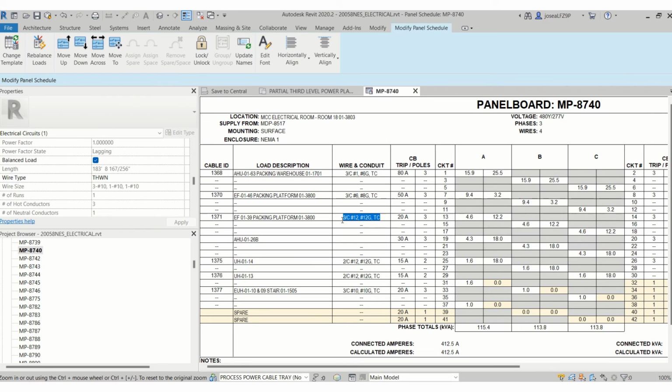We will copy these 3 conductors and then change that to number 10, a 10 underground, and we're using the TC cable, tray cable, for this. The grounding is different for each of the TC cables. So this is basically what you look for whenever you're sizing a breaker, disconnect switch, and the wire sizes.